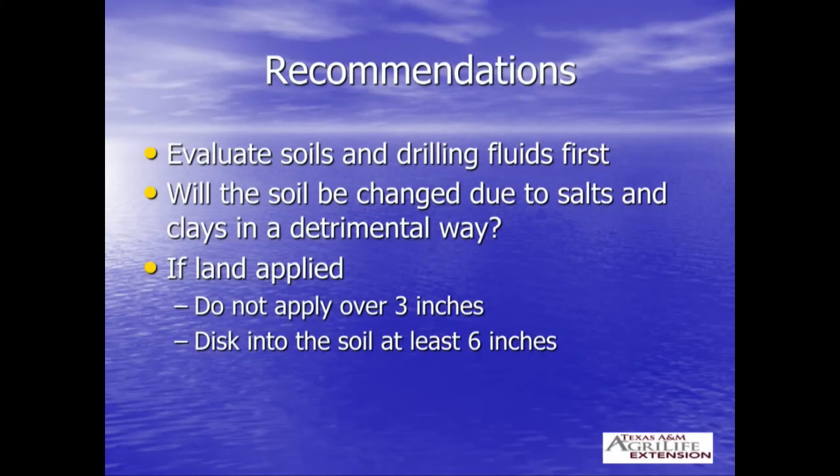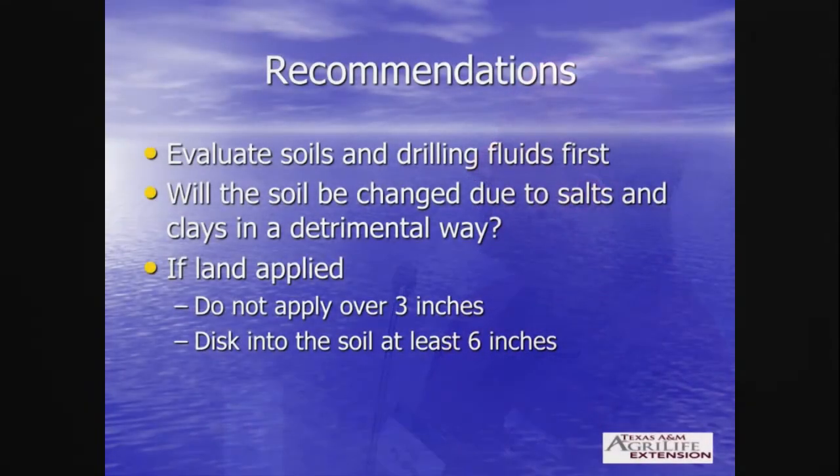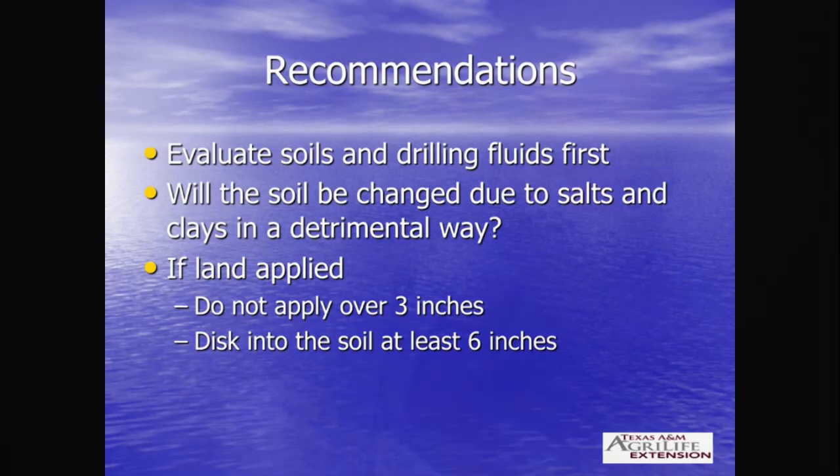So our recommendations: evaluate the soils and the drilling fluids first before you ever say, yeah, go ahead and put it out there. The drilling companies are supposed to have analysis, but again, they have analysis that meets the criteria for the regulations. We have some other things that we would like to see them analyze. And in Texas, sodium's a key, okay? And I think it would be here. I don't know whether it's required by Oklahoma or not. Will the soil be changed due to the salts and the clays in a detrimental way?